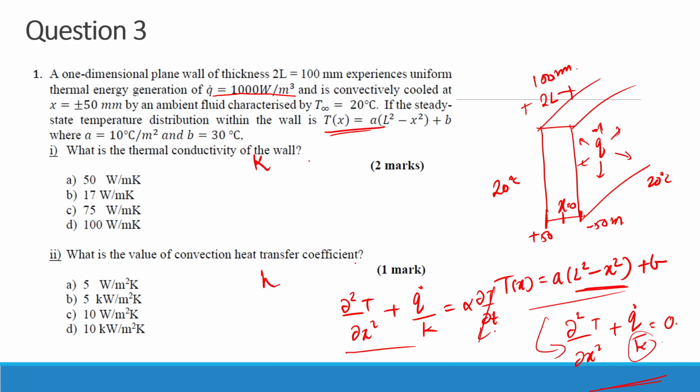in order to find the convective heat transfer coefficient. So right now it is 20:15. We will discuss the solution at 20:25, after 10 minutes. So this is the solution approach. You just have to put the values, then find the value of k from over here, basically differentiate this, put the value over here and find the value of k, and then write the heat balance in order to find the heat transfer coefficient.